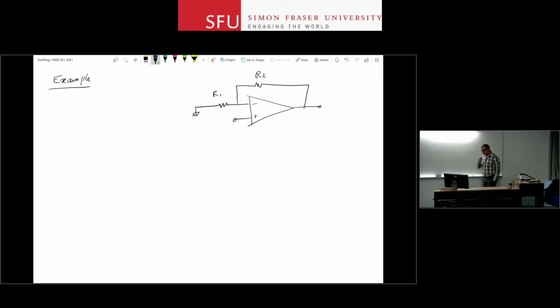So in many cases in electronics, you would like to have a circuit that sits between your measuring system, which could be a microcontroller, a voltmeter, or anything, and whatever you're measuring. What you want from this circuit is to faithfully translate the voltage from that node into something that is easier for you to deal with, and not affect the voltage over there.